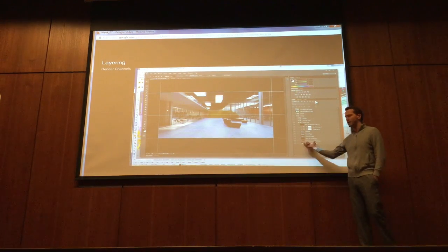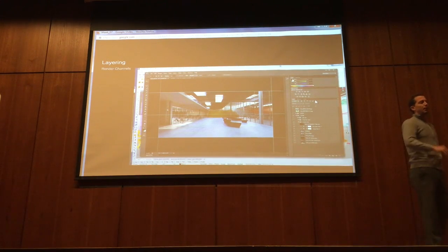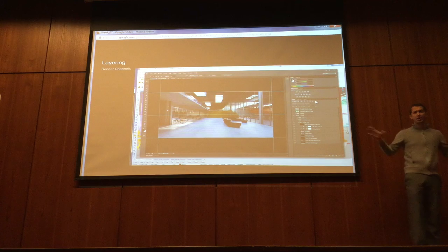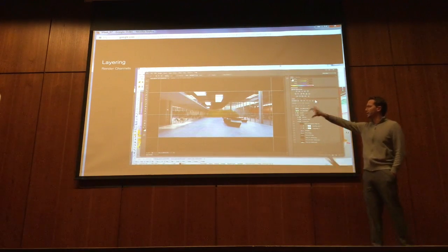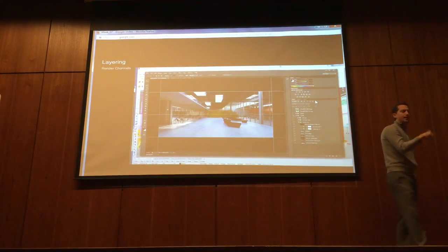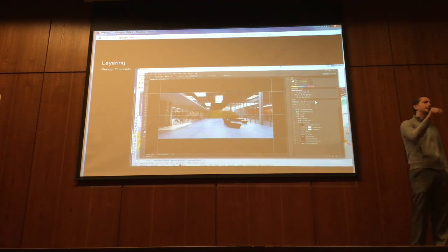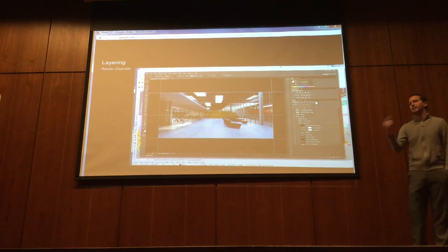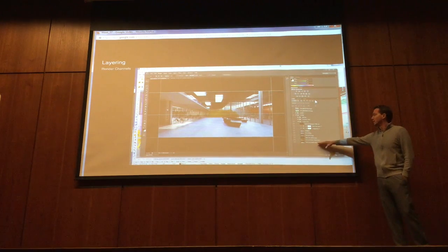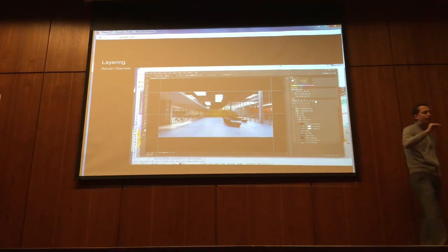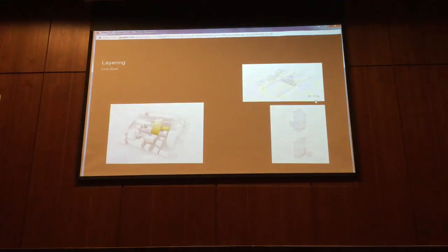The reason why you do that is because it's kind of like an XREF, it's a link. And so what you have is called a smart object. Now I re-render, I make some adjustments, I scale that thing, I move it around, and maybe I'm scaling and collaging it to fit in, but I re-render that image and I now have added materials. All I have to do is right-click on that placed object and replace the object, and it remembers all of those things that I've done. So linking is crucial for me. And also, if you right-click and copy to create a new one, you can do the same thing for all of your layer masks and your layer selections.